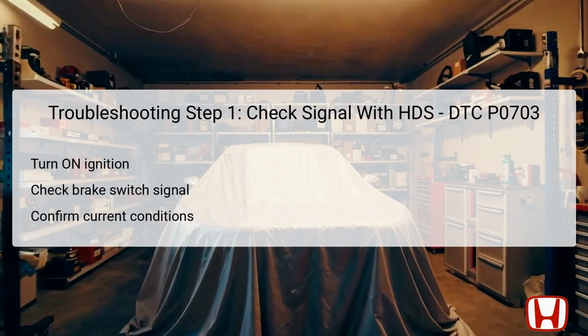The first troubleshooting step for diagnosing DTC P0703 involves checking the brake pedal position switch signal using the Honda Diagnostics System, HDS. Initially, you need to turn the vehicle's ignition to the on mode. The next step is to check the brake pedal position switch signal, ensuring that the brake pedal is not pressed.